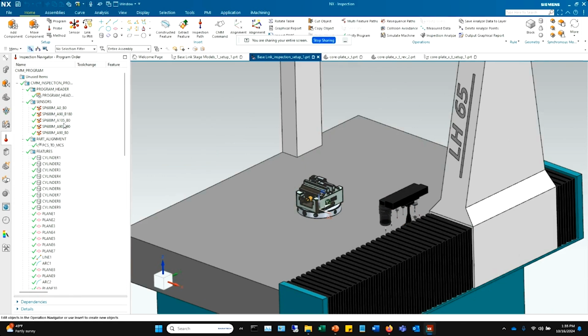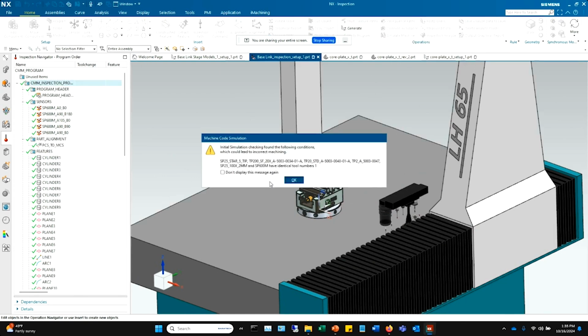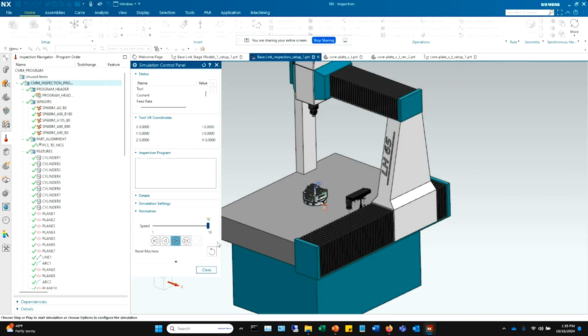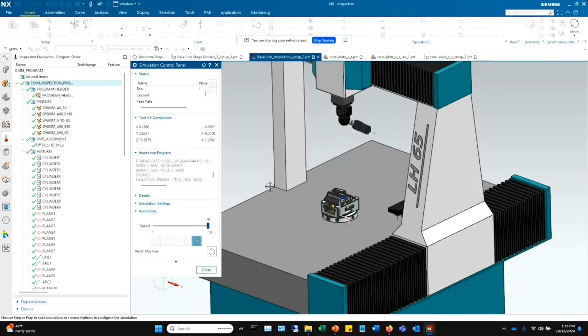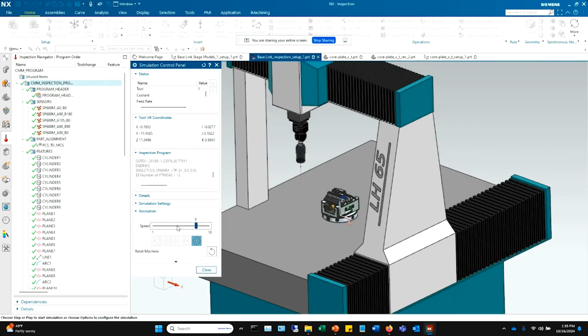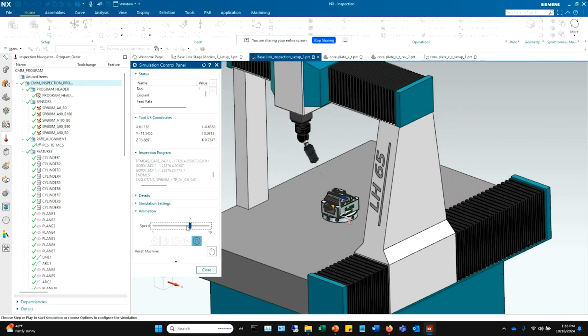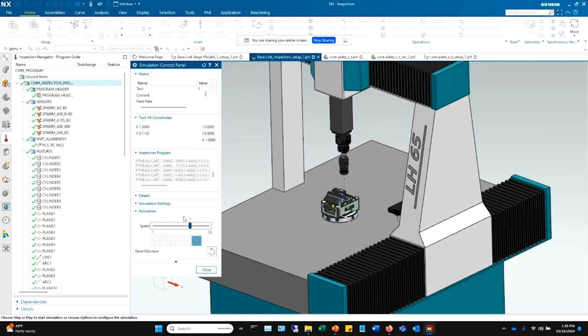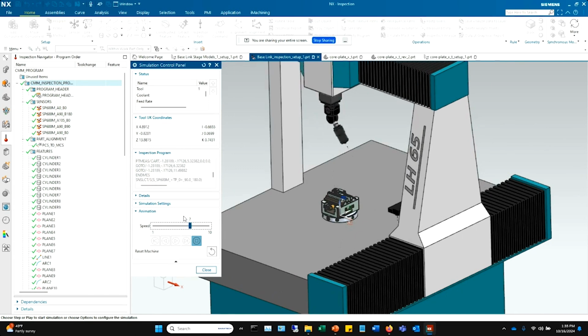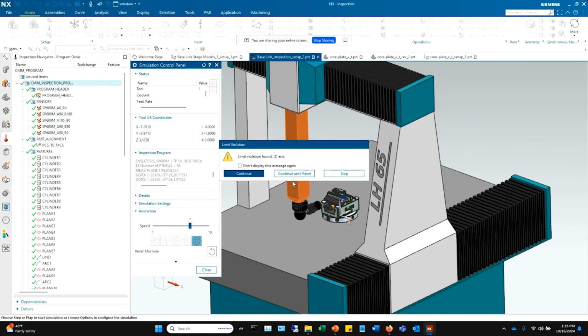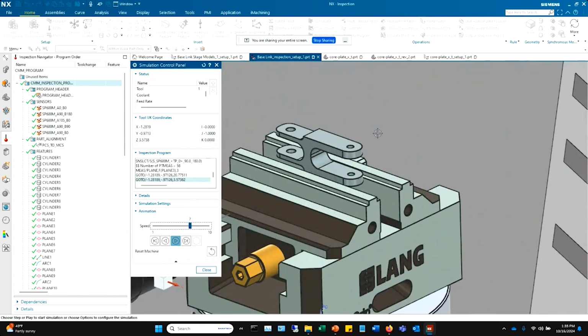This is the tool path that it had generated, the probing inspection path that it had generated. Now we have full G-code-driven simulation here. So this is what Mike was talking about with validating the tool path digitally before we go to the machine tool. Traditionally with our programs, we create a safety validation move where we will move this probe, and this here's our collision detection, 100 thousandths above the center of this circle and stop with an M0.